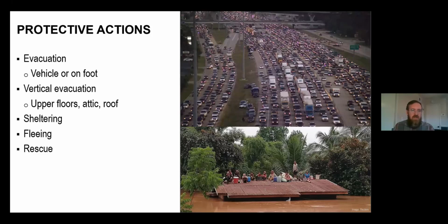Some people may be caught unaware and not decide to evacuate until the flood has actually arrived, in which case I use the term fleeing for that, meaning that they're evacuating through the water. And there are certain cases where that may be modeled. And the last is rescue, which is difficult to include in the consequence modeling software, but it is a consideration if you have helicopters or boats or things like that are really contributing to reducing the population at risk.